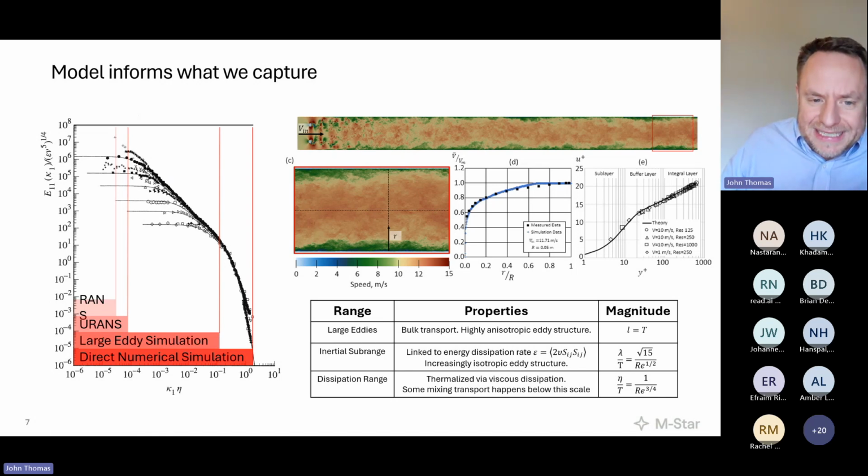So even though we're seeing less and less of this region over here, it is the place where the filter is designed to work the best. And we can reliably predict transport inside these large scale vessels, even with a large element size. In fact, here are some papers we wrote, some results we published on this earlier this year, where we looked just at wall-bounded flow and looked at how LES compared to DNS.